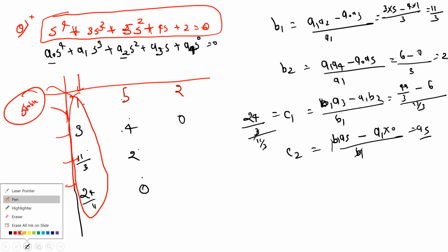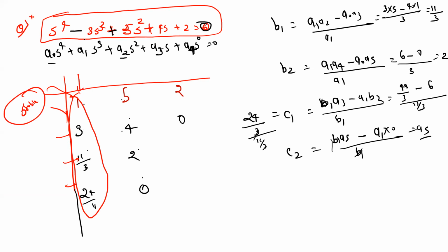So to find out if the system is maybe stable, may not be stable, you have to make the Routh array, right? But if, in place of positive, the sign would be negative, while observing this characteristic equation only, you can see there is a negative sign, then the system is unstable directly. But if it is positive, then the system may be stable, may not be stable. So we have to make the Routh array, and after that we can solve this particular thing, right? I hope this thing is clear to all of you. Anyone has any doubt?